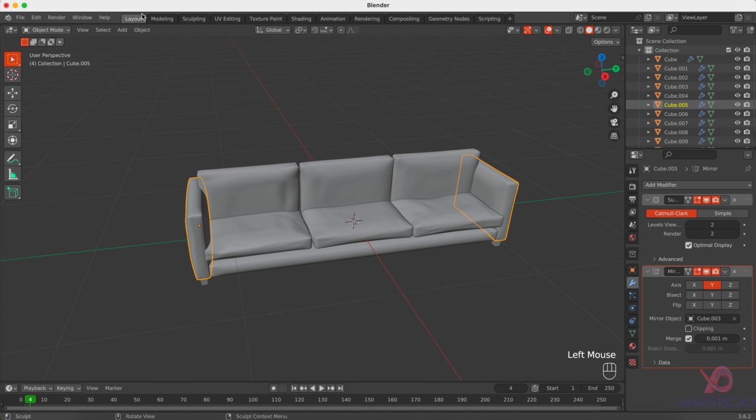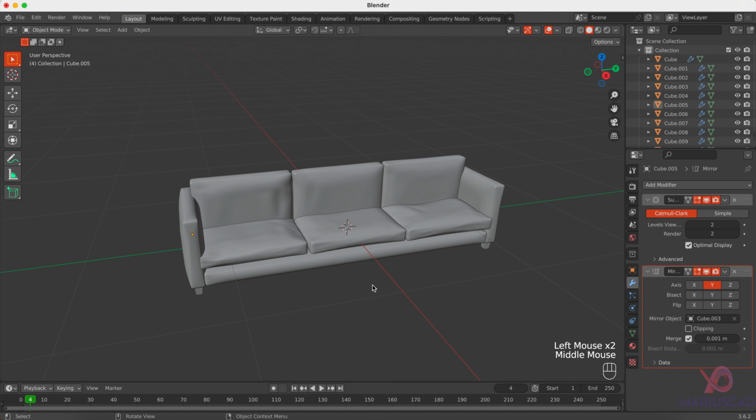To finish the 3D modeling, I will go back and I want to add 2 extra pillows. So 2 little pillows actually. In order to do that, I will create a new cube. So I'll go to Mesh, Cube, I will scale it. Okay. I will scale it now on the x-axis.